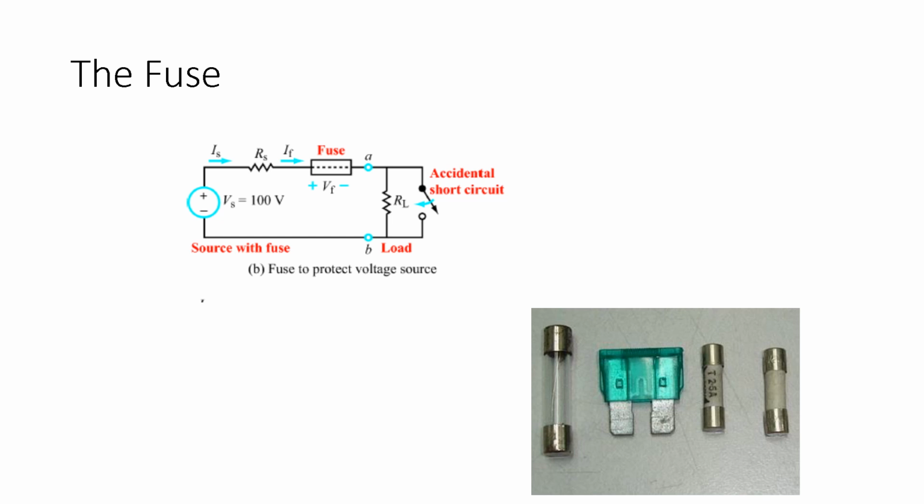And this goes really well for more high power electronics. So another one that we use a lot of fuses with is the electrospinning machine over in DEC. So that machine spits out between 8,000 and 40,000 volts of electricity. And so 40,000 volts has a high potential for something to short circuit because that's going to essentially create a spark gap.